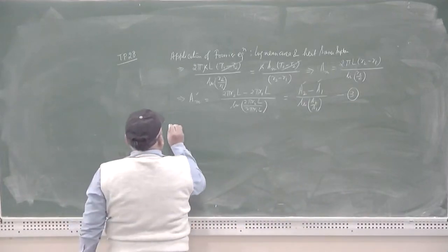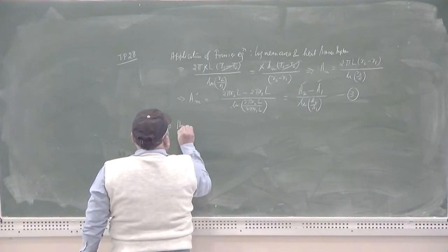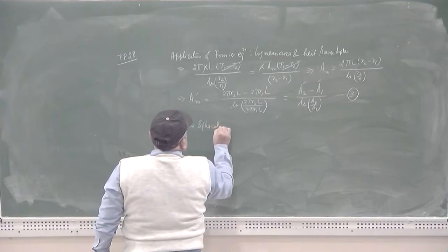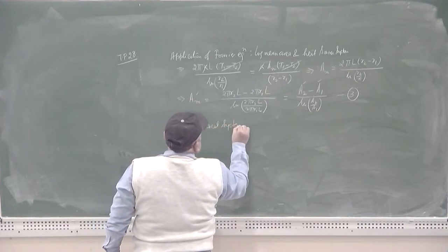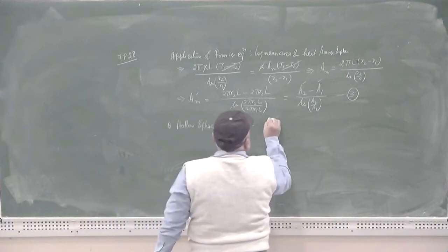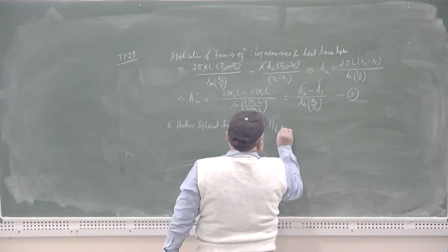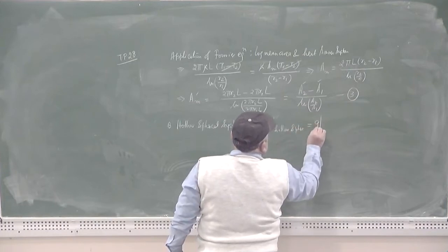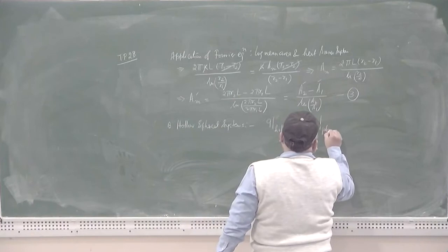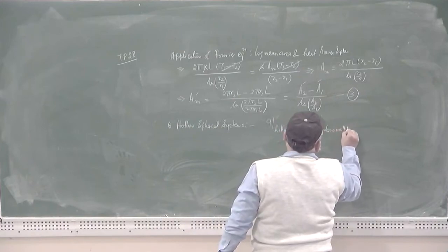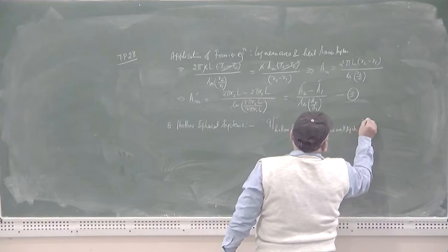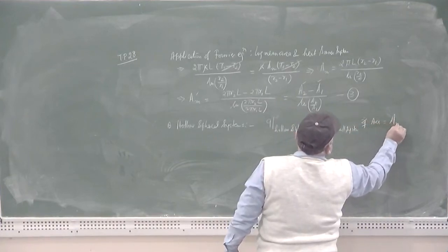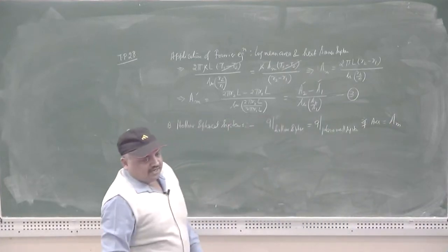So, in the case of hollow spherical systems, Q for the hollow sphere should be equal to Q for a plane wall system if the area of the plane wall is taken as AM, that is the log mean area.